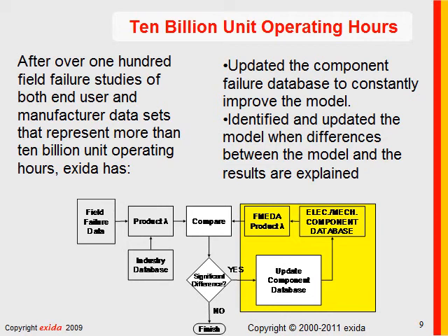I use the term field failure calibrated FMEDA data. What I mean by that is, let me back up for a minute. I remember back in the old days, the 1980s, when failure rate data for components came from a document called Mil Handbook 217. The most recent version that I ever used was 217F. We would look up the failure rates of resistors and capacitors and integrated circuits, and we would do board level reliability calculations, and we would come up with failure rates.